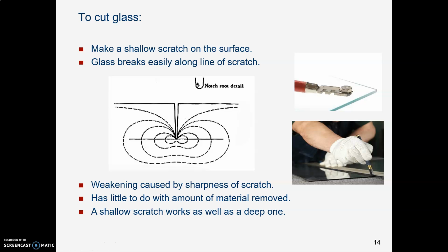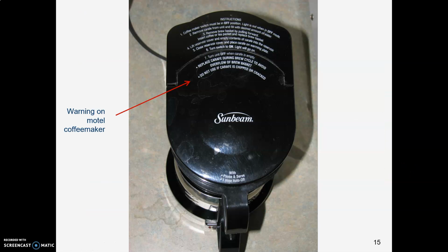Why does that work? Because you have created a crack where there's a stress concentration at the tip of the crack. It's a very small radius there, and it doesn't take much force out here at the end to cause that crack to propagate. This is a perfect example of how that works.